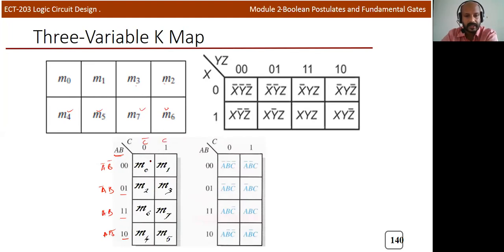So you'll get exactly the same result after simplification. But when you write the min terms, you can see that this is 0, 1, 2, 3. Instead of writing 4 here, we'll use in the last row 4, 5, 6, 7. In this way also I can. So some textbooks follow the second method and some follow the first one. I mostly prefer the first one. So when we discuss the questions, I will use the first format, 2 rows and 4 columns. If you're comfortable with the other, you can go for that also.